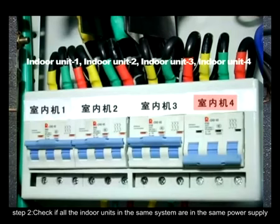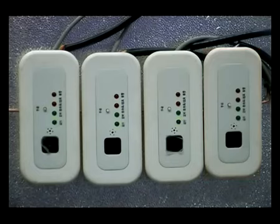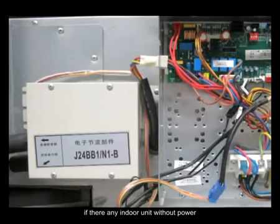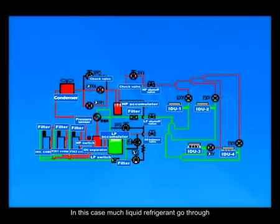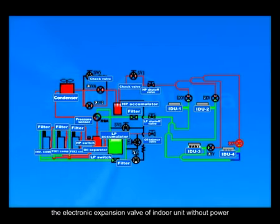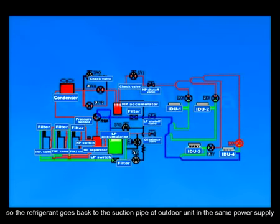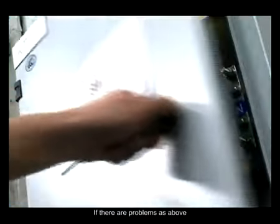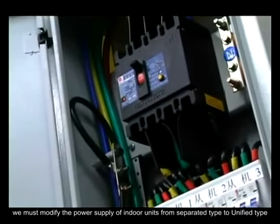Step 2. Check if all the indoor units in the same system are in the same power supply. If there are any indoor units without power and its electronic expansion valve keeps certain opening degree. In this case, much liquid refrigerant go through the electronic expansion valve of indoor unit without power, and the refrigerant doesn't evaporate and absorb heat from indoor side. So, the refrigerant goes back to the suction pipe of outdoor unit in the same power supply. If there are problems as above, we must modify the power supply of indoor units from separate type to unified type.